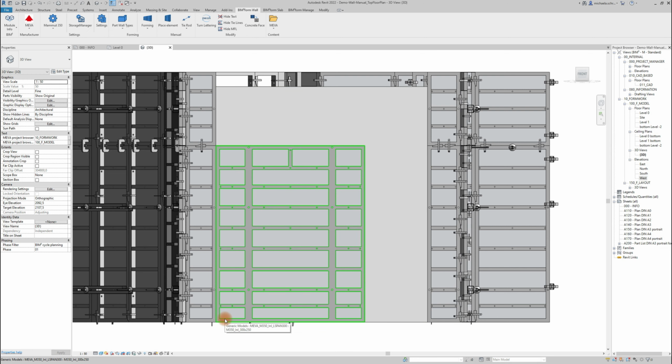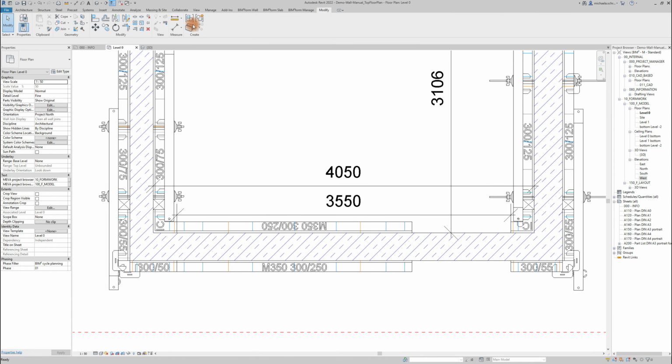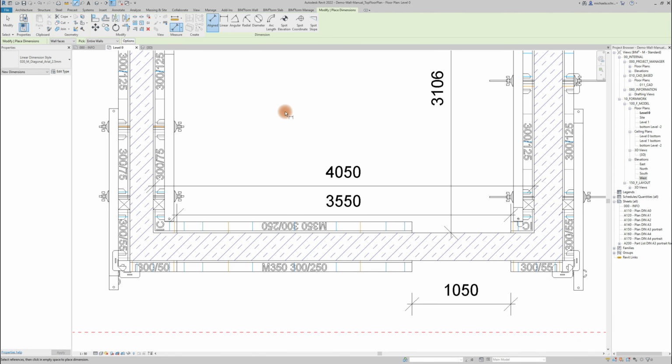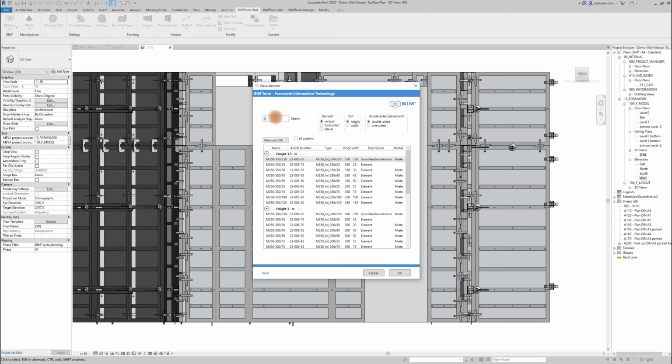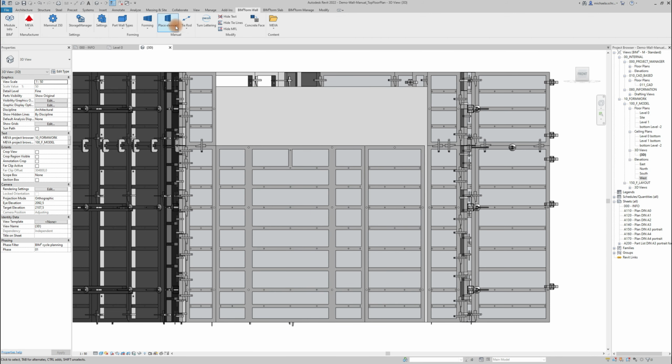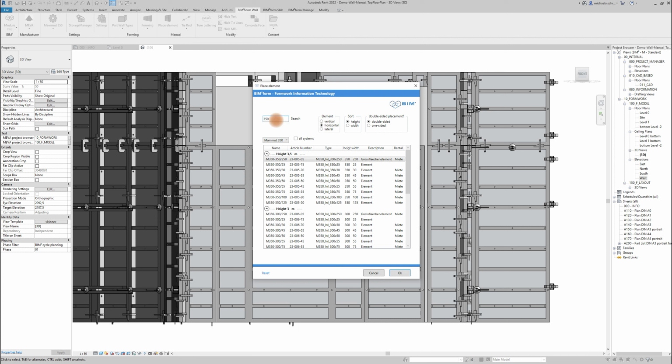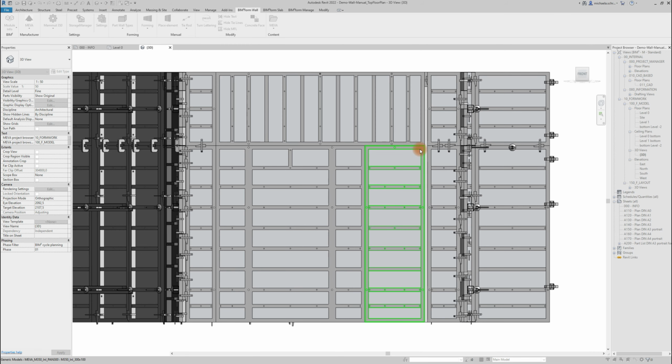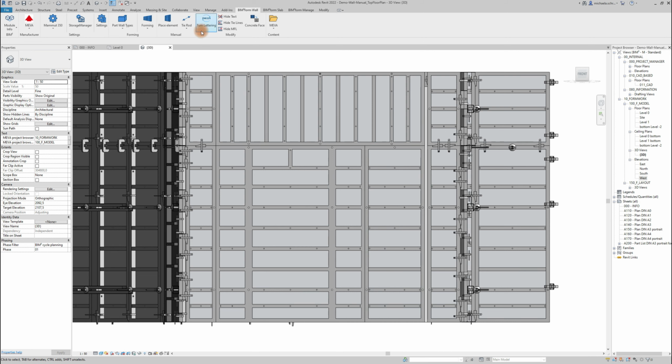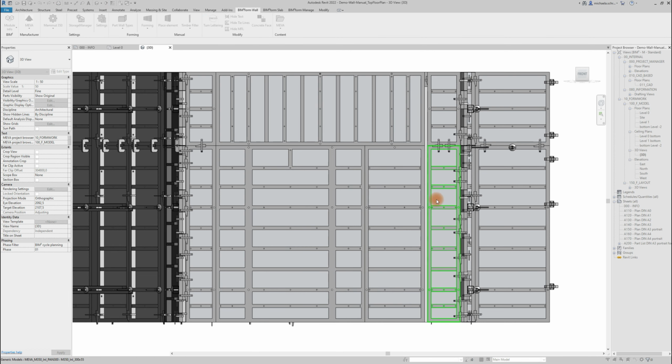For the gap, there is a bit more than 1 meter left, so we'll search for an element that has a 1 meter width and the same height and also place it next to it. For the top, we could place an element horizontally with a 1.25 meter width and a 3.5 meter height, and as I said earlier, we have to click the element below and the right corner of it because it will be turned to the left. We'll also place a slim timber filler in the leftover gap before continuing with placing accessories.